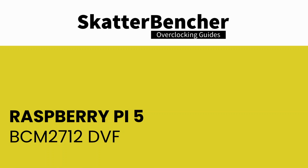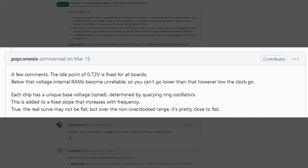One of the more interesting aspects of overclocking the Raspberry Pi 5 is uncovering its dynamic voltage frequency technology, or DVF technology. This technology allows the Raspberry Pi 5 SoC to scale its frequency depending on its needs, and as the frequency increases, also the voltage increases. Each BCM2712 chip has a unique base voltage, Vpred, from the factory. This base voltage is added to a fixed DVF slope which increases with operating frequency.